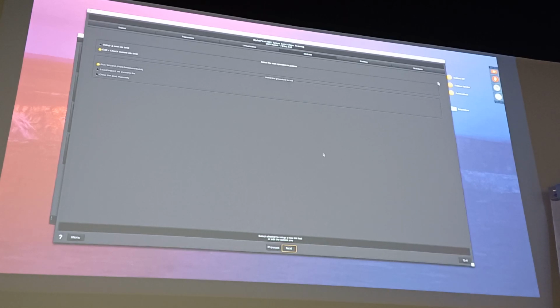So we are arriving to the last step of the calibration, which is the ink limit. Then we will go through the profiling, which is all about colors. The ink limit is very important because it will define how much ink the substrate is able to support. So this will set up your maximum quantity of ink to print at the same time for one specific output color.